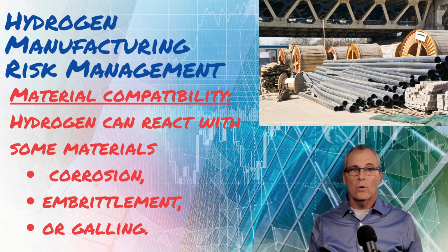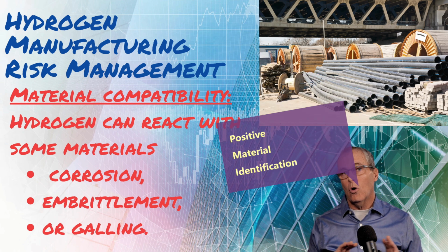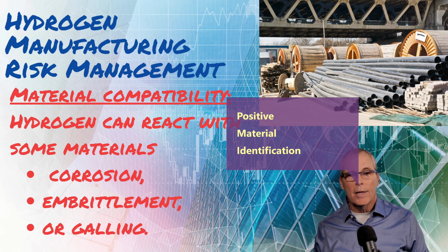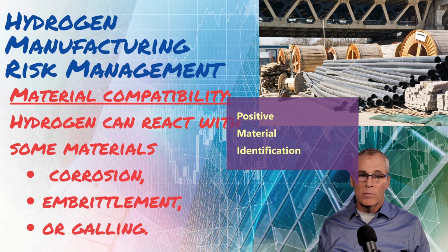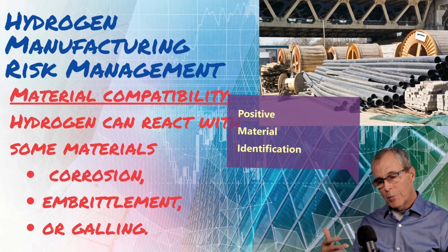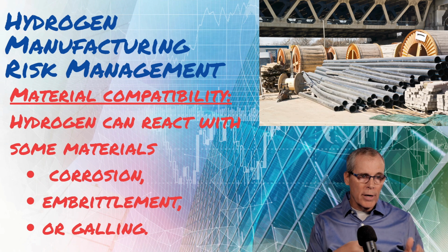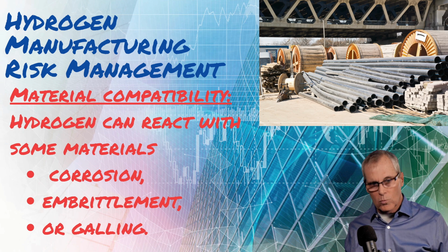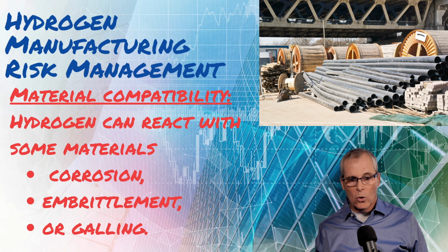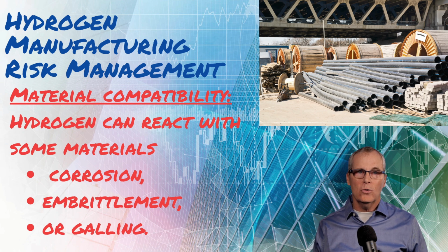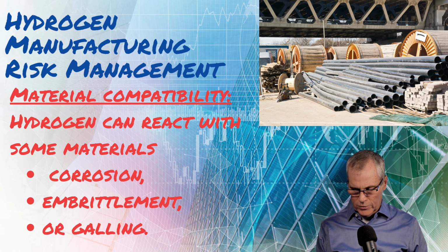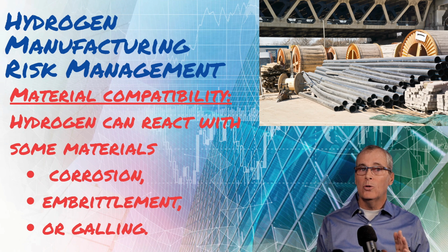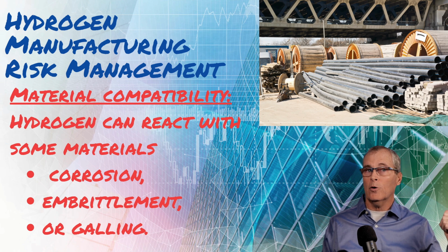There's a process called positive material identification, PMI, a whole complete program in facilities with PSM. They even have PMI guns where you can put the PMI gun on your material, and it will use lasers and technology, and it will tell you what your material is. So, there's really no reason not to have a good understanding, especially in newer facilities that are being built now, exactly what you have. Now, just because it's new doesn't mean that the manufacturer's checking the material compatibility.